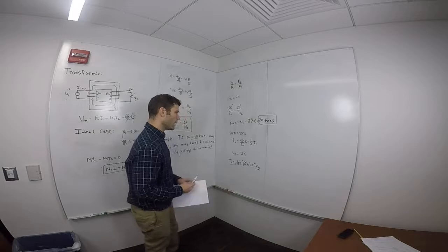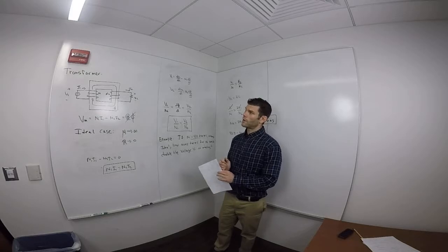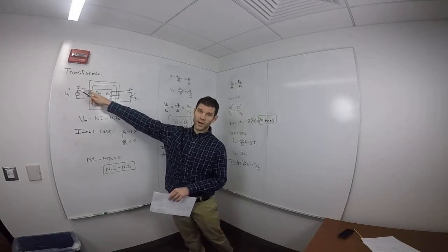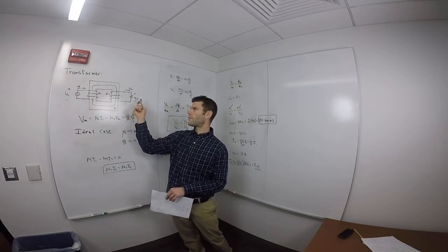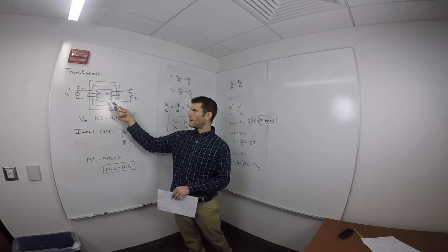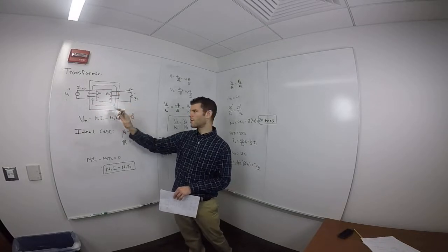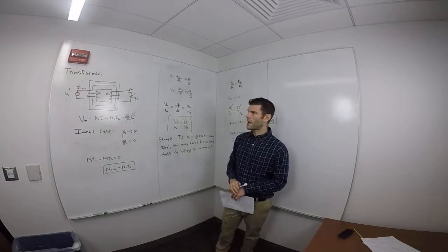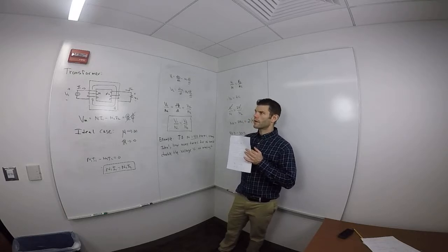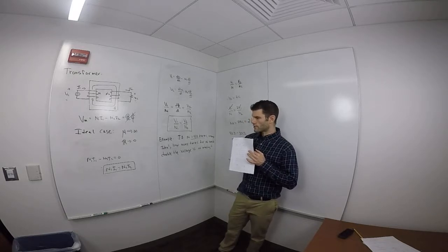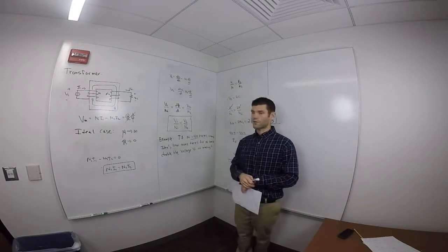Okay, just one quick caveat is that this is an ideal transformer, so actually we're going to get some power dissipated by these windings in a real transformer, right? These windings have some internal resistance, so we're not going to get exactly the same power here. We also have what's called hysteresis and eddy current losses through the core, so they'll also dissipate some power, right? So you're not going to get exactly the same output power, because you're going to get some of that power consumed by some of the parameters here. But none of those are considered in the ideal transformer. So in the ideal transformer, you should have output power exactly equal to input power, or we could say the transformer is 100% efficient.